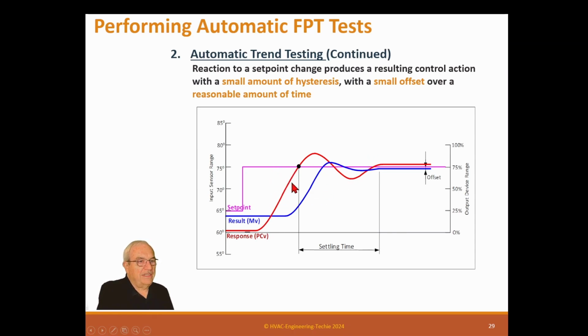The second one is the integral band, and that actually is calculating the area under these curves. Between this line and this, it's calculating the areas of the curves. And what it's trying to do is, under each successive one, make it smaller. And the final one is the derivative band, and it's actually telling you what the slope of this line is. And it's trying to get this slope to be flat. So those are the calculations.